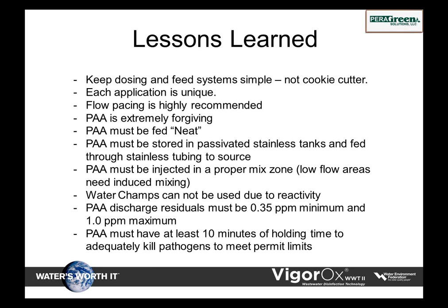Polyethylene, HDPE, fiberglass, the PAA acts on the plasticizers and will soften it up. Okay, you will be replacing that material. To date, we've tested hundreds of products with Solvay's research folks and also outside suppliers, and have not found anything other than stainless that will hold up and give you the safety and security that you would need for feeding this. It also has to be injected in a proper mix zone.